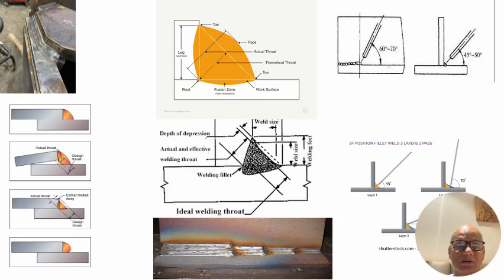So what is important for us, which we'll be saying in our third slide, is where the stress concentration is going to happen, and where after welding there will be an internal stress which is going to develop because of the shrinkage. Like in a butt joint, there is shrinkage. Here also there is shrinkage, and it is said that if you take two plates at right angle to each other and try to put a tack there,